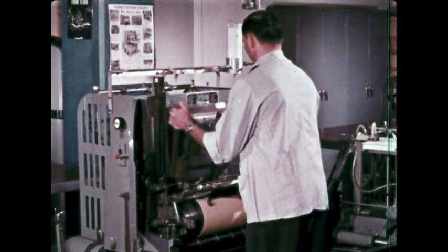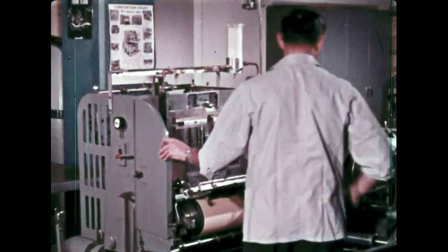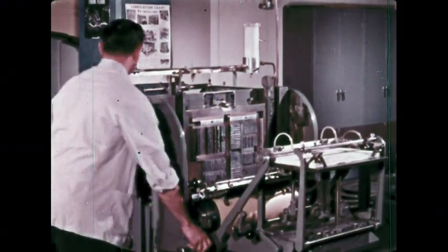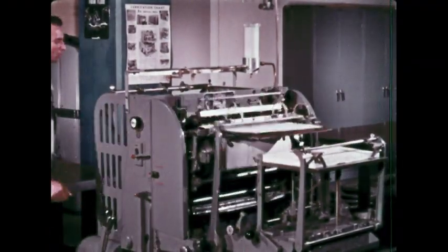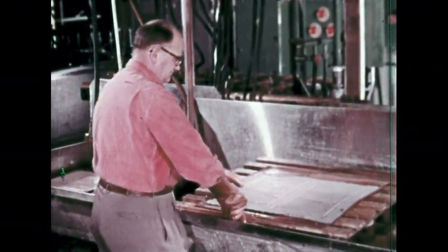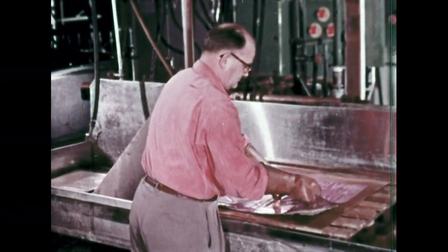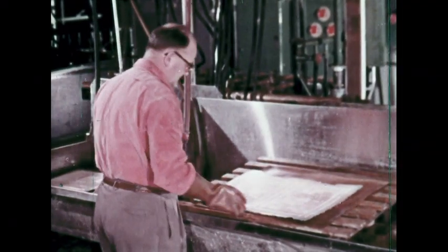When a job calls for extensive use of type, letterpress is generally used because with this process we can go directly from typesetting to press without the intermediate steps the other processes require. This, of course, is true only if the run is a short one. When letterpress is to be used for long runs, or when duplicate plates are necessary to permit runs in many publications at the same time, electrotypes may be made. These are plates cast from a mold made from the original plate.